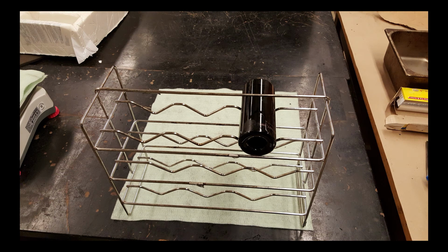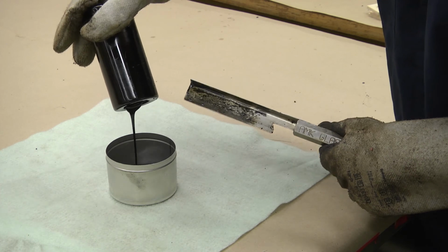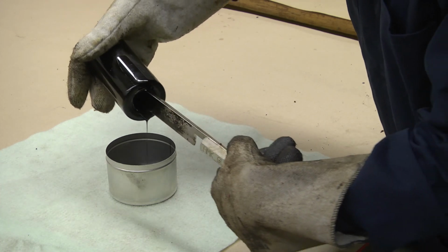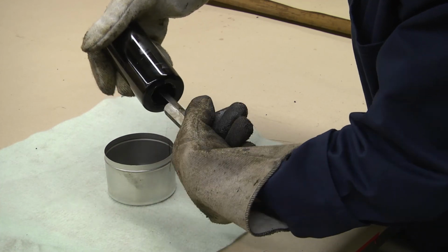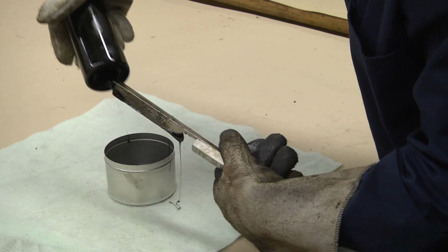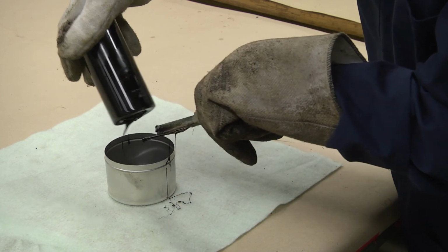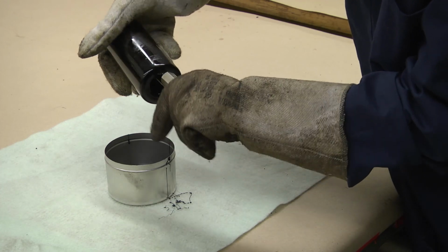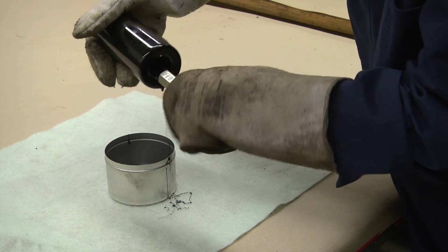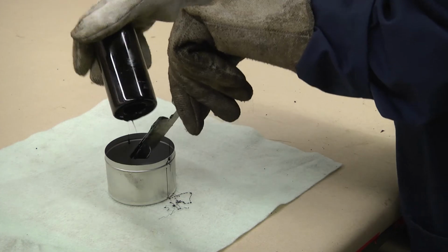After 85 minutes of conditioning, remove the bottles from the carousel, setting the mass change bottles aside to cool for 60 to 180 minutes. Residue from the remaining bottles should be transferred to a single container. Remove residue from each bottle by first pouring as much material as possible, then scraping the sides of the bottle to remove any remaining residue. The RTFO residue collected is used for rutting characterization in the DSR and for further aging in the PAV.